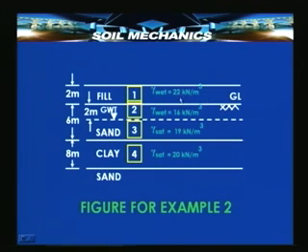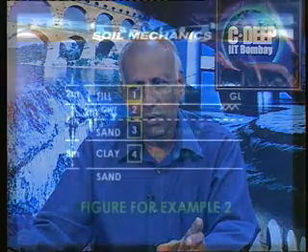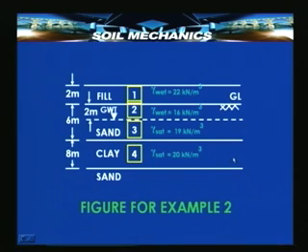Therefore, the top two layers numbers 1 and 2 are moist or wet layers, whereas layer 3 and layer 4 are both below water level and therefore, are completely saturated. This detail is important for computing the initial state of stress that exists in the clay layer.